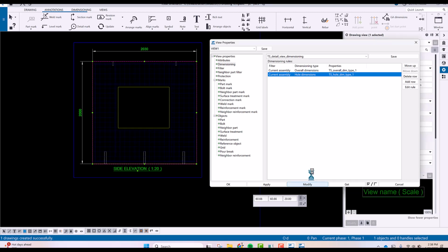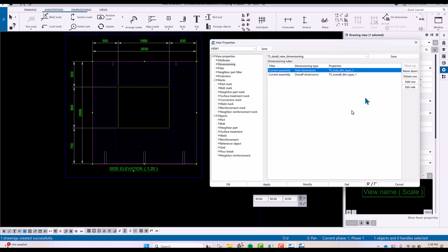Again, this is one time. You do it one time only, because once you set all the settings here, later on, no need. You just use the view here. I will show it to you. Now, if you notice here, the dimension of the hole is outside. So if you want to interchange the position, for this hole, I need to put it up, modify, move up, and then modify. Look, it will change to the other way. This one, see? It will interchange, right?